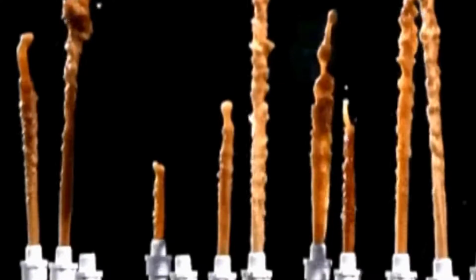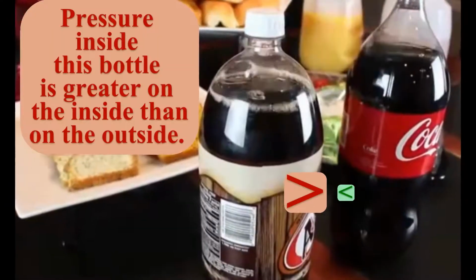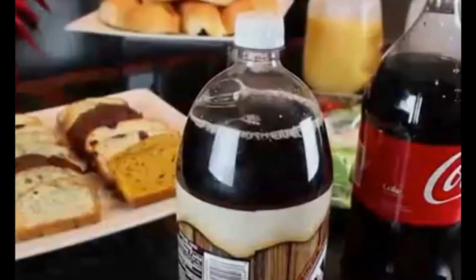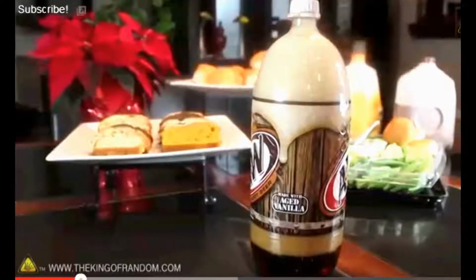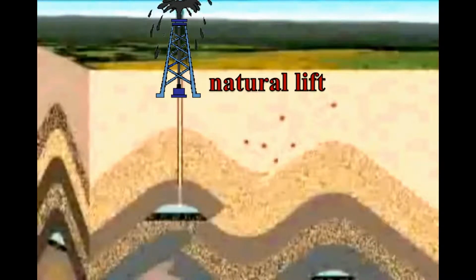Let me show an example that you are all familiar with that will help illustrate what I'm talking about. Take a moment to visualize a column of a carbonated beverage as it explodes upwards and outwards. If you remember from your high school science, the pressure inside this bottle is greater than on the outside in underbalanced conditions. This pressure differential remains in equilibrium only until the cap is removed. On removing the cap, the pressure differential releases energy from inside the bottle. It carries with it the carbonated liquid that spews up and out. The same thing happens inside a reservoir, and this release is known as natural lift.